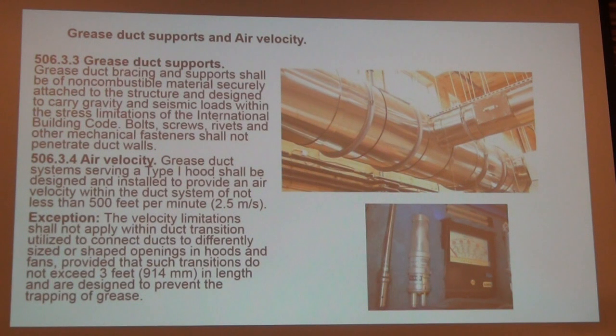The 3 things were secondary air for dilution air, but the 3 things was in case of a blockage in the vent, that the products of combustion would be relieved out of the diverter instead of out of the bottom of the appliance where impingement would come.